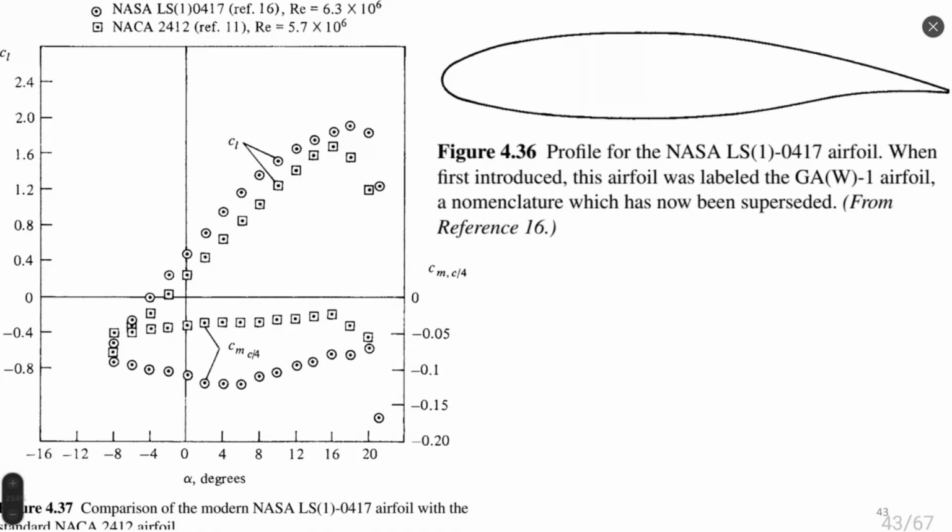And when we divide by the maximum, which is 2, we can say that the improvement of lift coefficient achievable due to numerical optimization is close to 15–20%. So this is a realistic value of what we receive by optimizing an airfoil numerically.